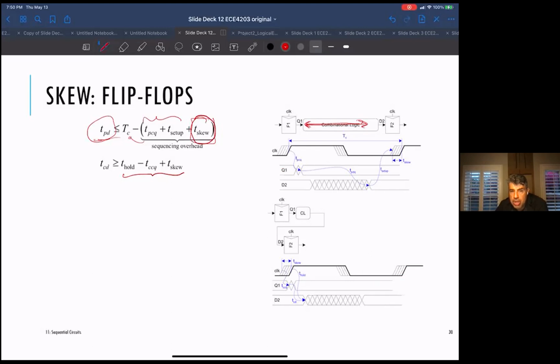Then your place and route tool will place the logic, and you run a timing analyzer on the final result, and it'll tell you that you've missed your timing. It'll give you, say, 1,000 paths or whatever number of paths where, because of clock skew and delays, you don't meet your timing.